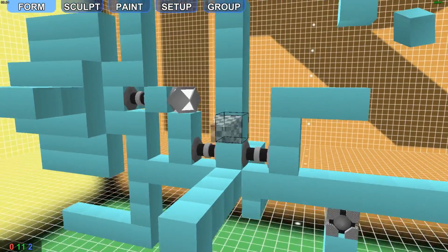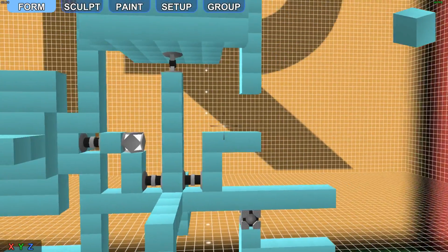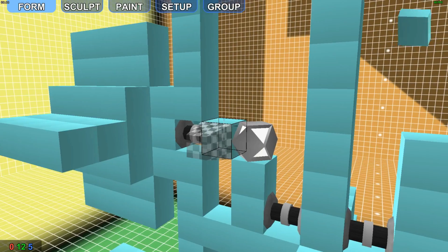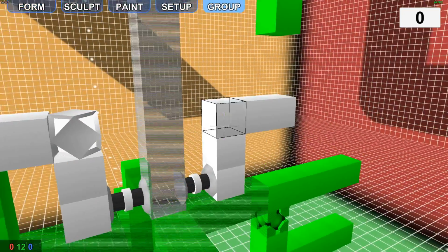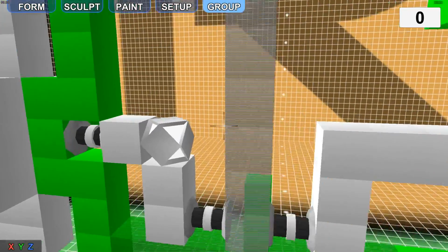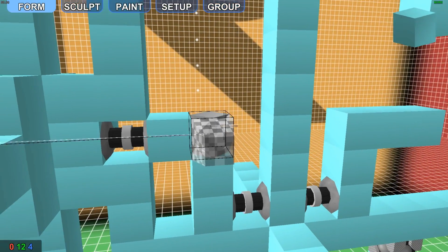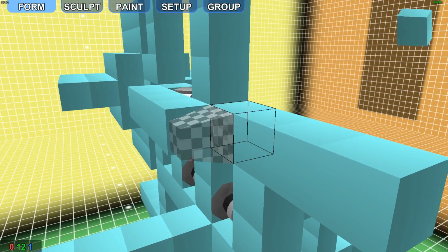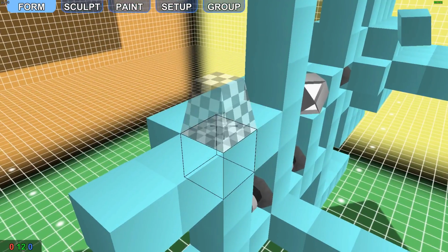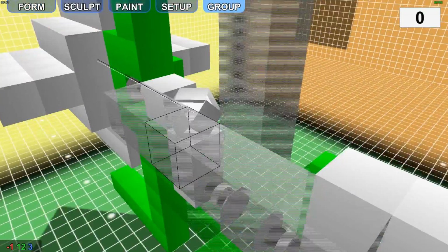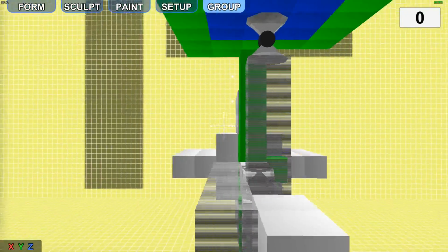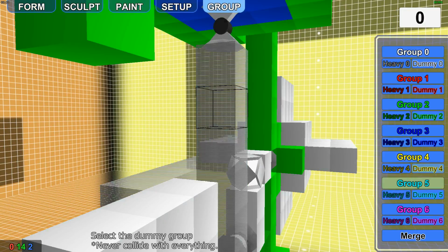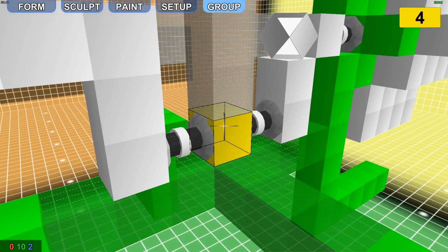Now with having two of these cylinders, this linked section, I discussed it earlier, but we do really need the brace so that this can transmit power across the entire crankshaft. And then when you do that, since these are the same group, they'll collide, so now this has to be a different group. So you definitely need to make sure your grouping is correct, or it's not going to work at all.